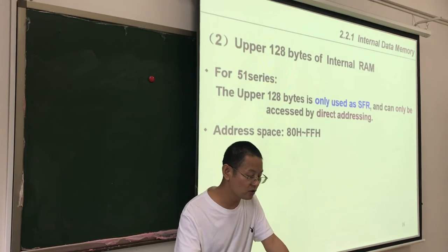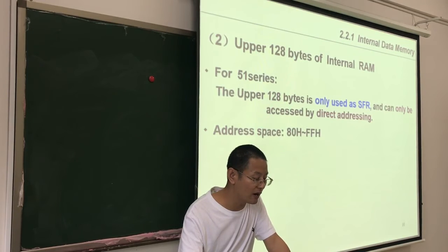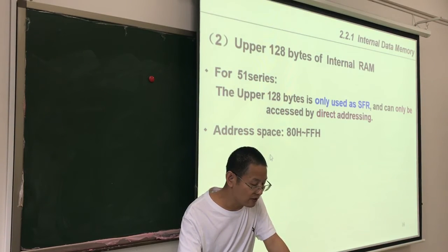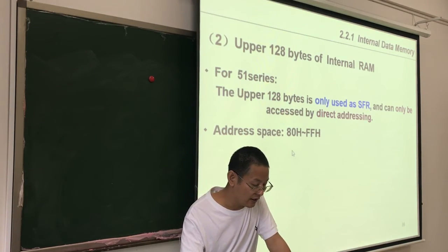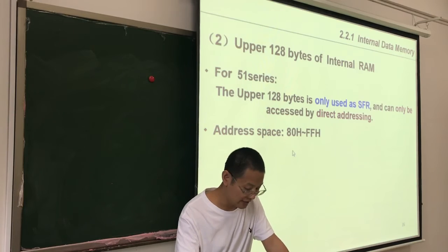Upper 128 bytes of internal RAM. For the 51 series, the upper 128 bytes are only used as SFR and can only be accessed by direct addressing. Addressing space 80H to FFH.